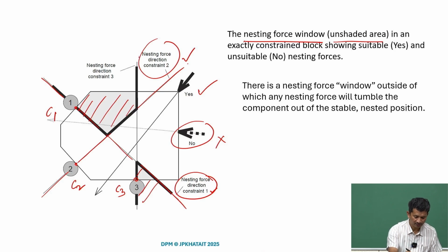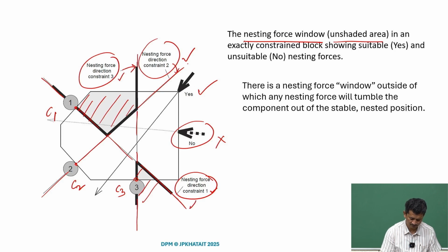Similarly, if we pass through point C3, this is because of the contact C3. So these are the constraint directions. What we also understand is that if we take 2 of these contacts, they always create an instantaneous center of rotation. So we can find ICs.